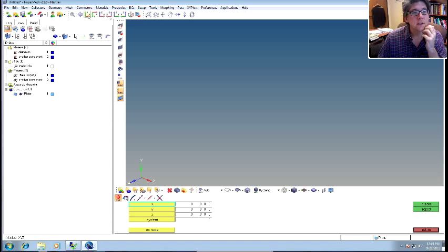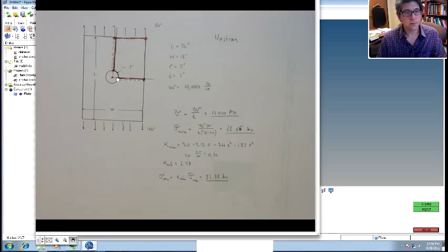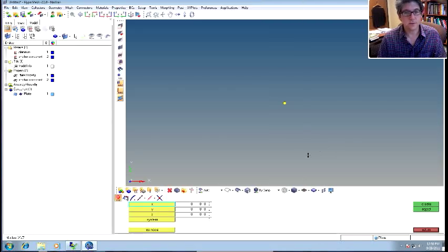Let's change the orientation. So I'm looking down the z-axis, okay, and here's the node I just created. That's the center of the circle. So let's make this right edge point of the circle. So we'll make this point, so that's going to be at the radius, and then 0, and then we'll go out here to W on 2, so on and so forth.